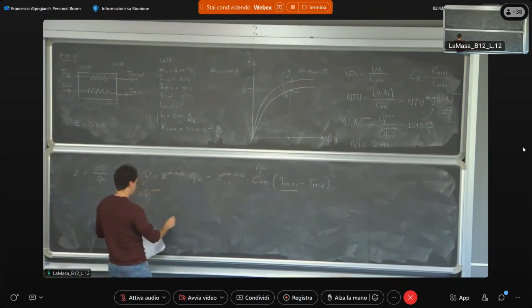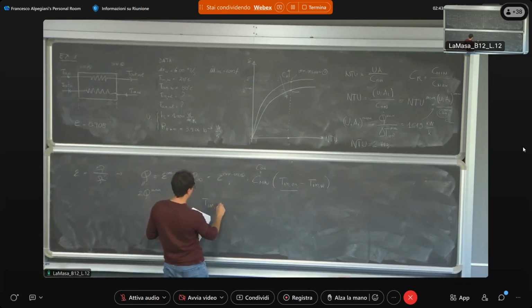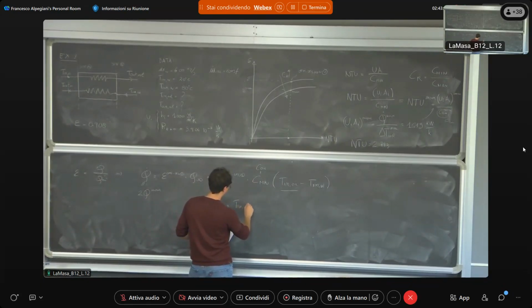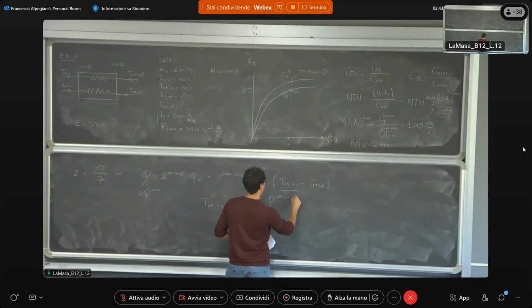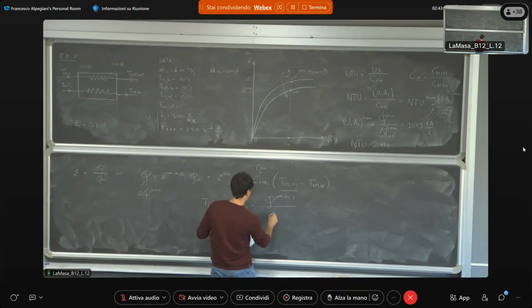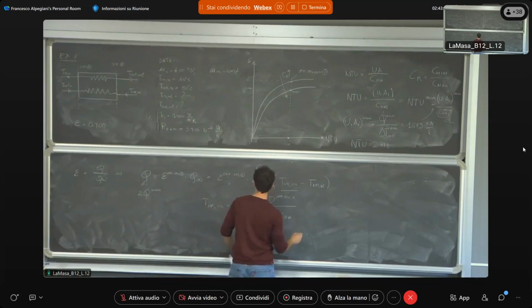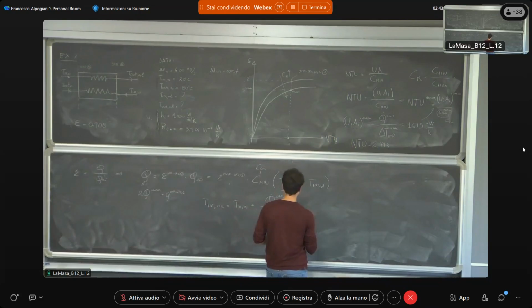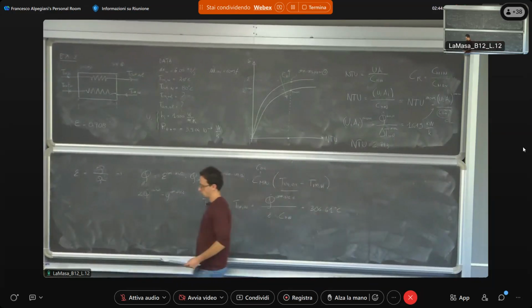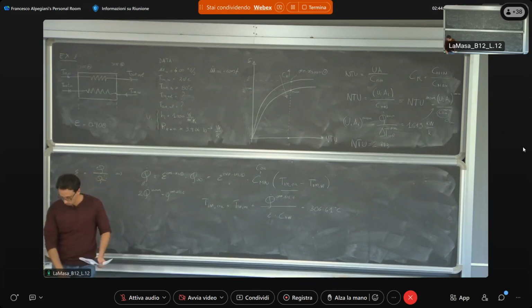So we can evaluate it, reversing the equation: T in of the oil is equal to T in of the water plus Q in off design condition divided by epsilon times C min, where this is Q. And so from here we evaluate a temperature of the oil at the inlet, which is 306.41 degrees Celsius, greater with respect to the previous one, which was 170.